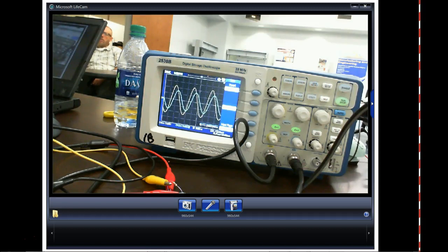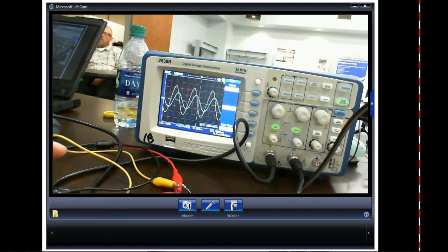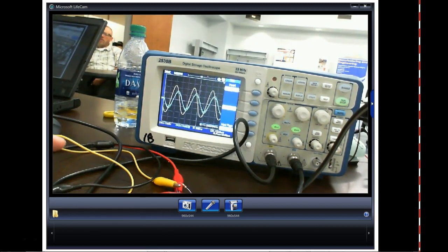So what we do is we start the motor and then we click out the start winding. There's what they call a centrifugal switching. So this is a capacitor. All I'm doing is changing the overlap of this thing. And you can't hardly see it, but I'm not only changing the phase shift, but I'm also changing the voltage drop across the resistor, which is pretty neat. So that's all I'm doing, is changing the capacitance.